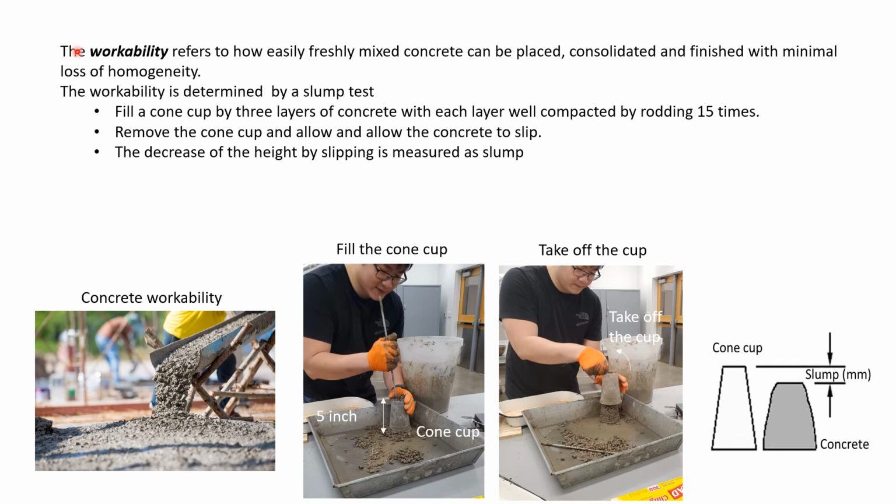The second property we care about is the workability of concrete. The workability refers to how easily freshly mixed concrete can be placed, consolidated, and finished with minimum loss of homogeneity. It is very important in the construction field.